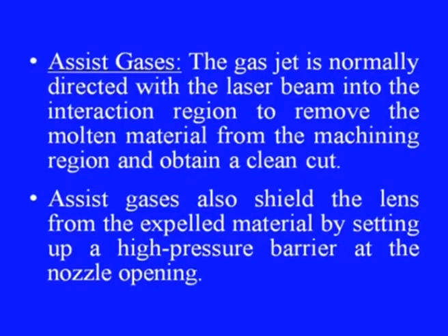Another important component in the laser beam machining, as we have already indicated, is the assist gases. The gas jet is normally directed with the laser beam into the interaction region to remove the molten material from the machining region and obtain a clean cut.